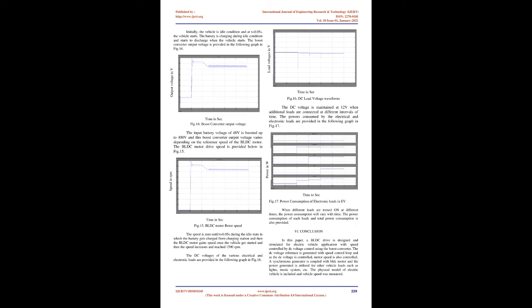The step signals are used to turn on the loads. The power consumed by each load is measured along with total power consumption. The torque from the BLDC is provided to the generic engine, which in turn is coupled with the vehicle body, and when the BLDC motor starts, the engine also starts to operate and hence the vehicle starts to move. The simulation circuit for the engine along with gear setup is provided below in Fig. 12.a. Fig. 12.a: simulation diagram for physical modeling of electric vehicle.